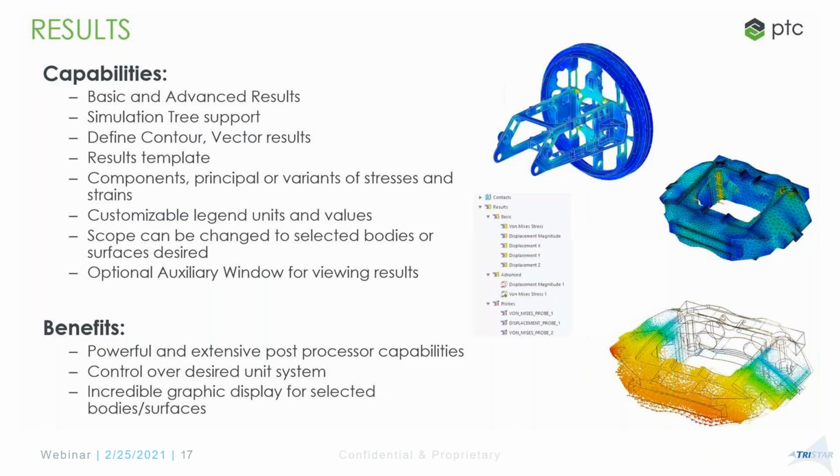And finally, the results. The results can leverage GPU. So if you do have a good NVIDIA CUDA-based graphics card, even though the solver itself is using the CPU, the results could use the GPU if it's there. It's not a requirement, but it can leverage that. You're able to look at various plots and add additional probes. There are simple, basic and advanced types of results. I'll show you a little bit during the demo in the next half hour or so. You can also look at the mesh with the results.